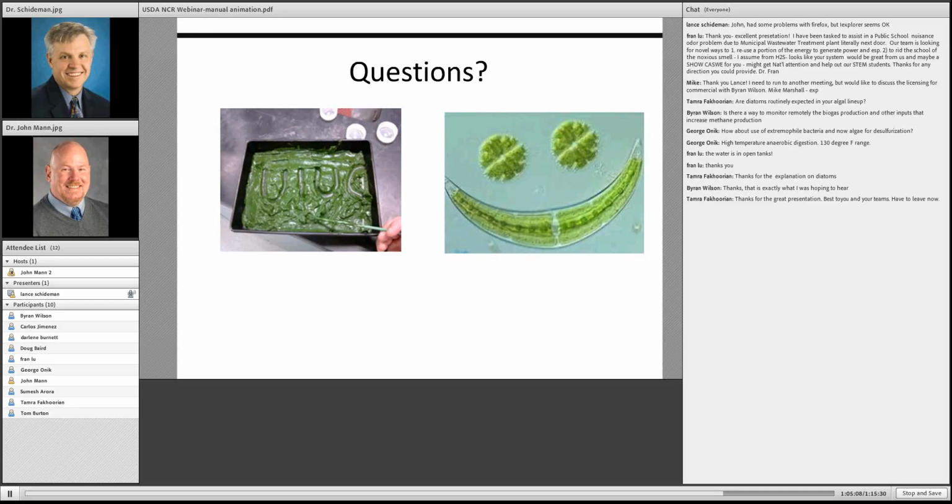But yeah, most of what we've done has been at the mesophilic range because the bacteria are a little bit more robust and hardy in that range. The thermophiles are maybe a little bit more efficient, but they're generally known to be more fussy, and you've got a parasitic energy load to get up to that higher temperature that's greater. So usually the balance can be made, but it is a trade-off with the mesophilic temperatures. If I didn't answer your question, feel free to shoot another one back. But those were the thoughts that came to my mind based on the words on the page.